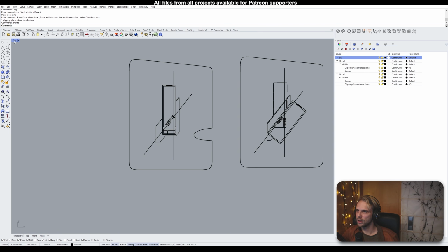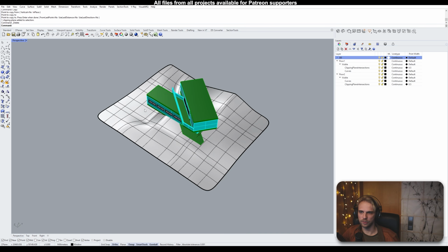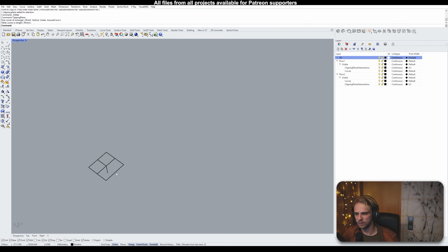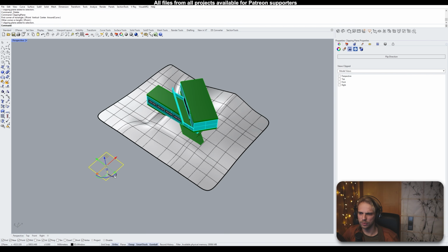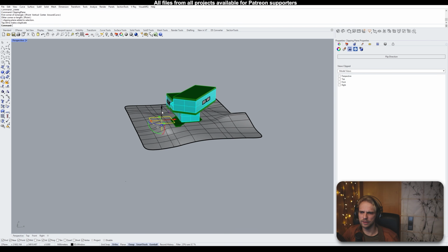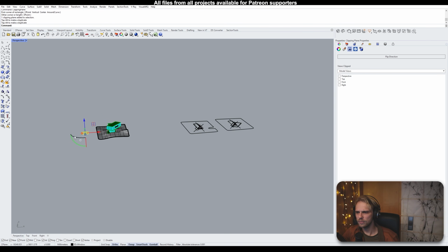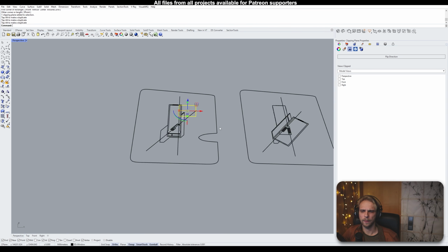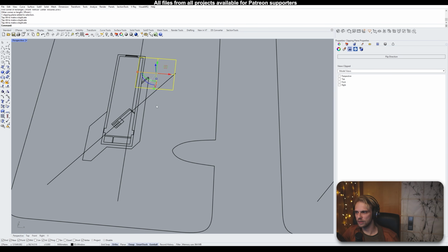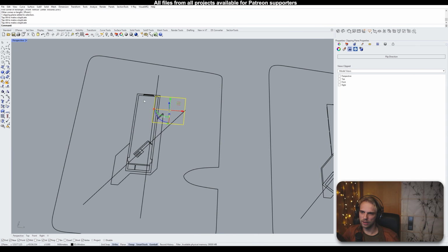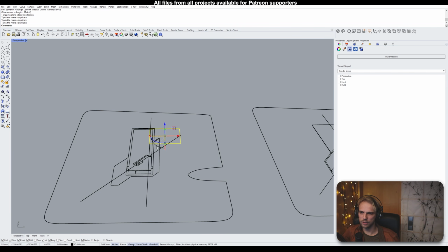Well, in the perspective view, we create a clipping plane again. I could have used the same one, I apologize. I will go to the properties of the clipping plane and turn it off so that it doesn't clip stuff. It's easier to orient it. I'll move it to the clipping line or whatever it's called right here, and I'll rotate it so that it aligns properly.